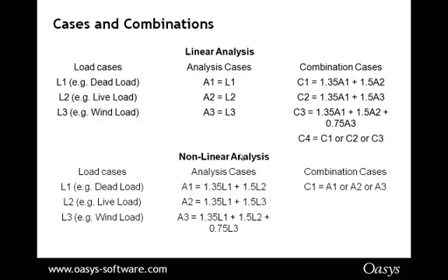With nonlinear, you have to multiply and combine the various load cases as part of the nonlinear analysis up front. And so in the combinations, it's only appropriate to do an envelope. It's not right to do combination cases where you multiply and add nonlinear results together, because the results will not be accurate at all.